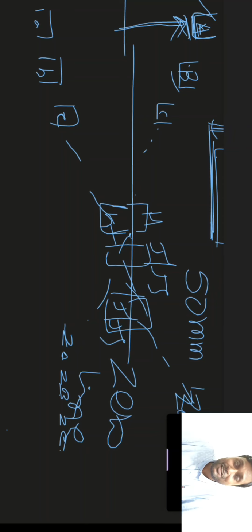Suppose that we have to manufacture a hole of 50 mm diameter. Then for 50 mm diameter, for this A type of fundamental deviation, this value will be fixed by a formula provided by ISO 286-1988, or you can say IS 919-1993. These two codes are similar. The Bureau of Indian Standards has accepted totally, without any change, the code of ISO 286-1988.